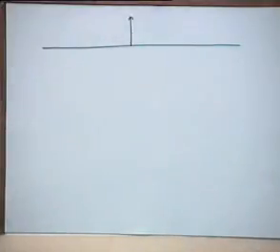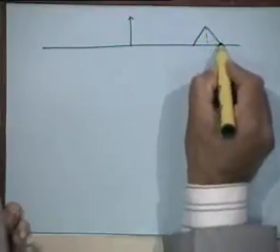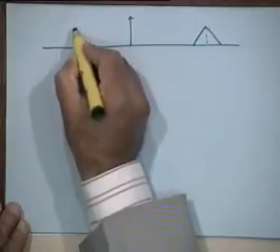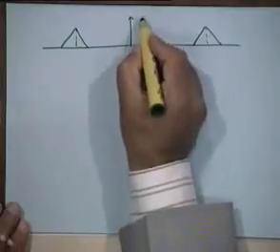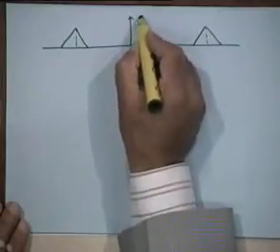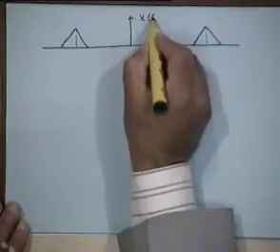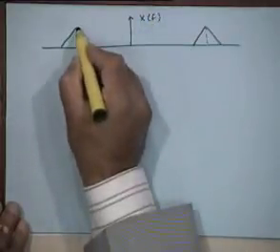I want to write an expression for the SSB waveform in the time domain, but to do so I'll start with the frequency domain, because an SSB signal is very easy to understand in the frequency domain, not so easy to understand in the time domain. So let me start from where it is easy to understand. As we know, we can generate an SSB signal by starting with a DSB-SC signal and then low pass filtering it.